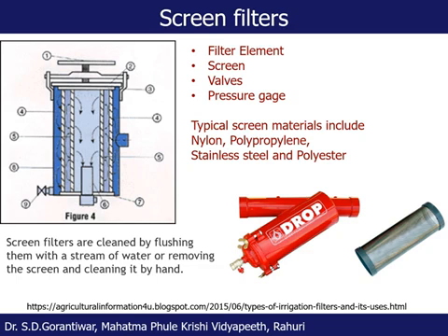In fact, for this it is better to open the screen filter, remove the filtering element, and then wash this filtering element against the high pressure stream of water, or just clean by hand actually. And in the downmost I have shown the filter element. Here this is the screen filter element and casing as well.